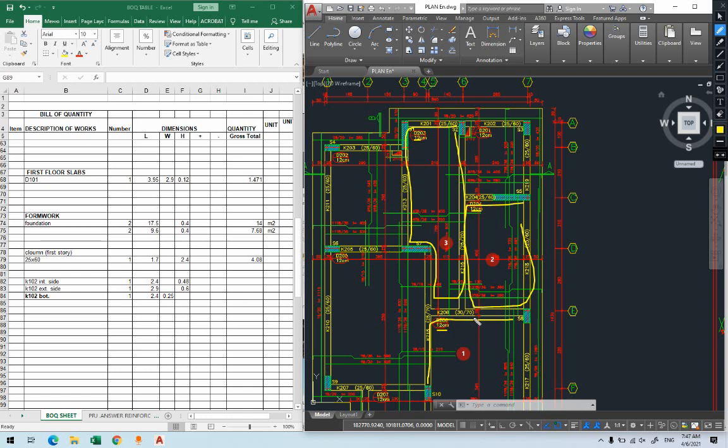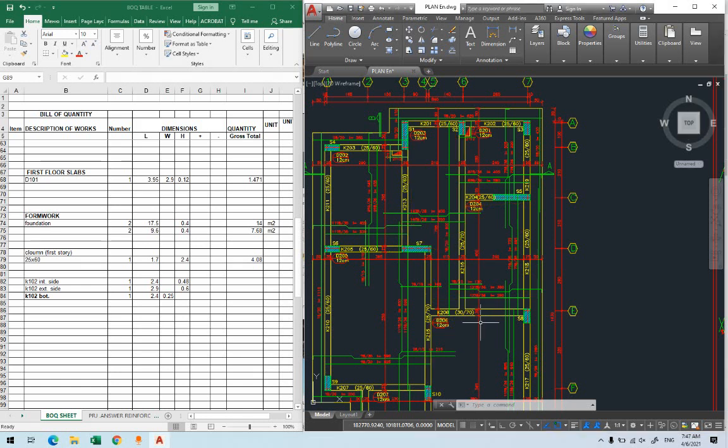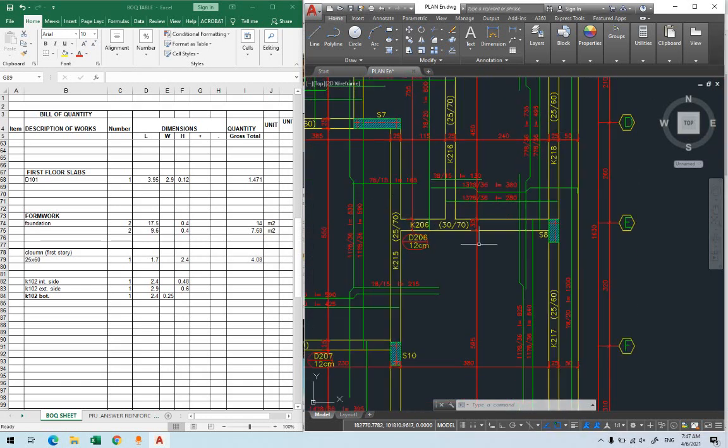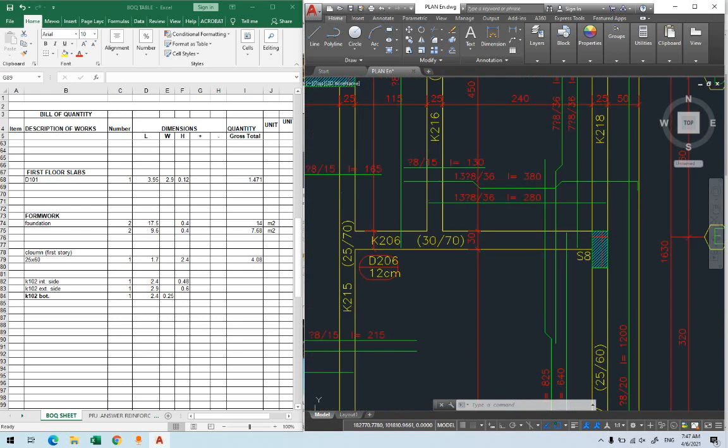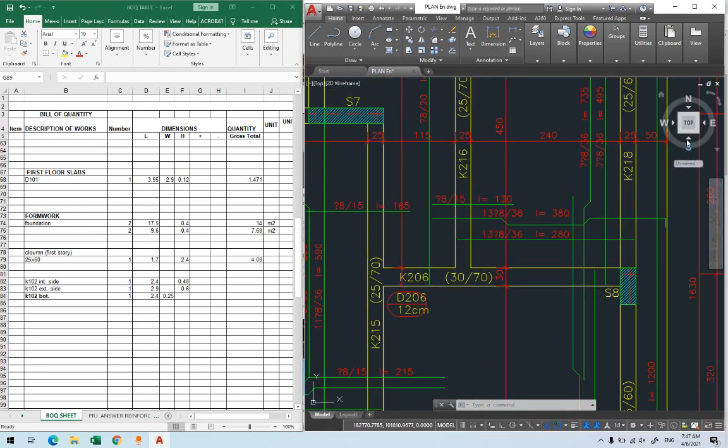All of them will be the same, which we have 70 minus 12, so we have 58. So 70 is the height of the beam minus 12, the thickness of all the slabs the same. That's going to be 58. We'll use it for the height of the formwork, for the side, remember, for the side. So we'll zoom in. We need to calculate this. We need to find the dimension, which will be provided to us by someone.